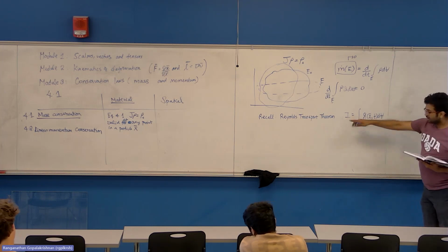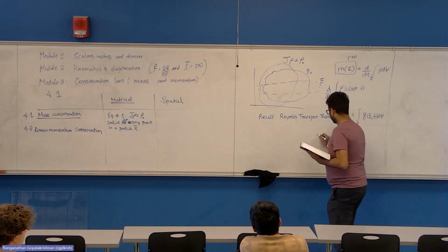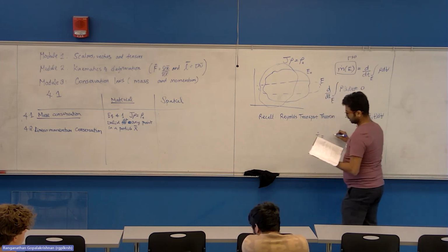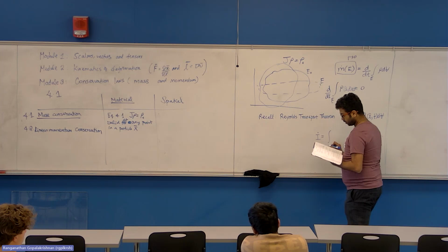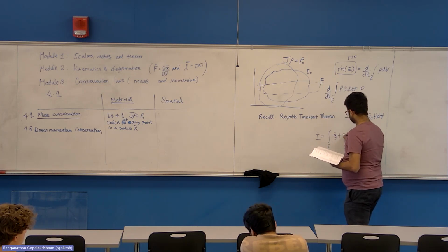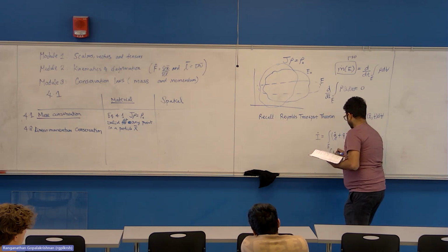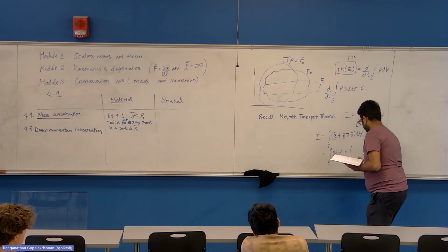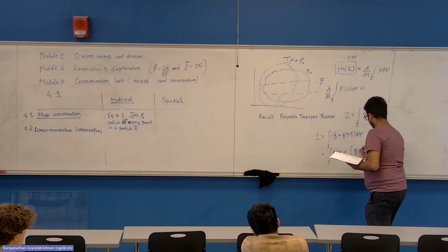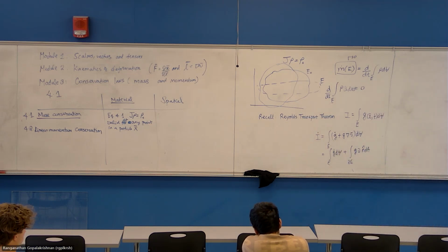If I is a quantity which is the integral of g over a certain volume, then I dot, the rate of change of I, is given as the integral over E of g dot plus g divergence of V dV, or it's also equal to the integral of g dot dV plus the integral over the surface of g V dot n dA. We can take either form.